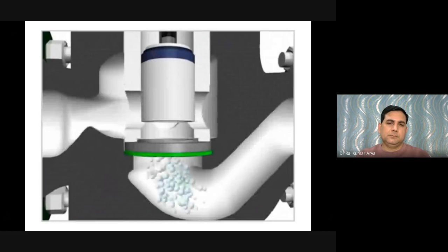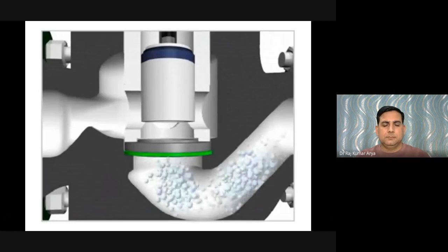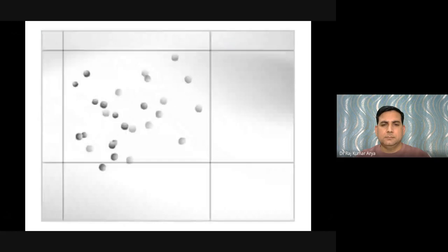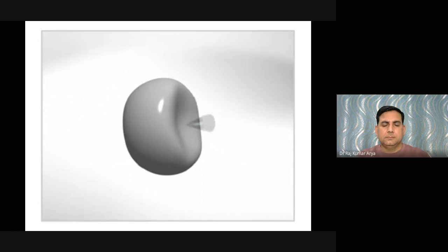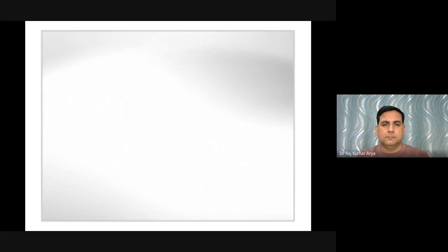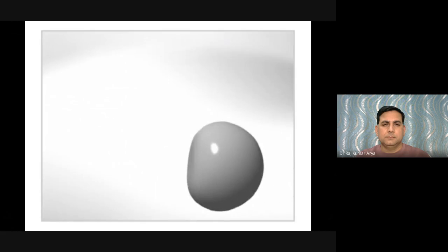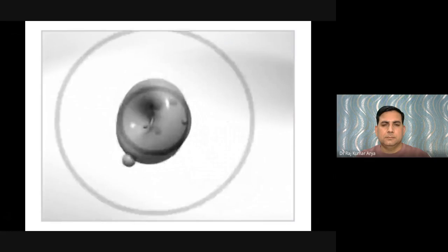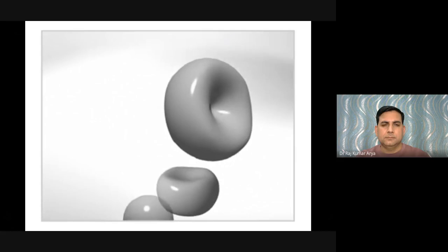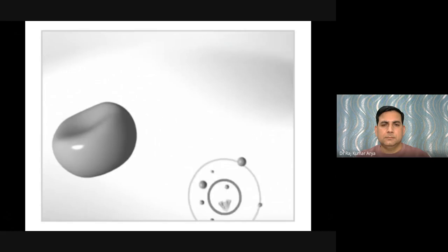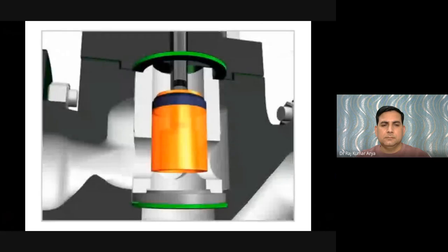Liquid microjets form when the recovering pressure makes an indentation in a bubble. Then the microjet bursts through the bubble. These implosions can also cause local pressure waves of up to 100,000 pounds per square inch. The combination of pressure waves and microjets can cause severe damage to the valve plug, seat, and body when they're located near the material surface.